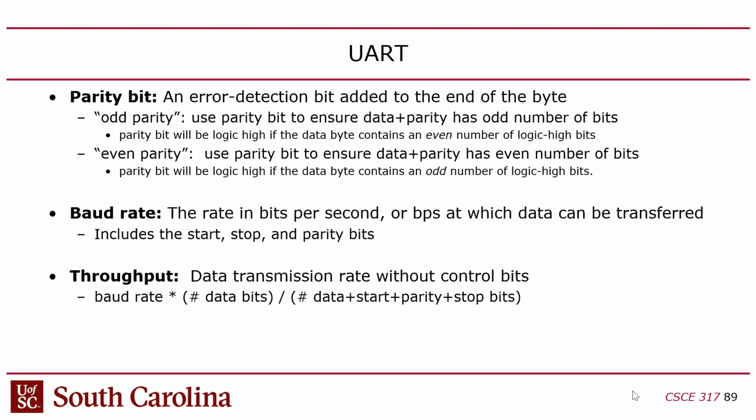Luckily, in this day and age, and in my experience, usually it's 8 data bits. Actually, there could be a different number of data bits too. I didn't mention that, I should have. Normally there's 8 data bits, but technically you could have more or less. But 8 data bits is the standard. No parity, and 1 stop bit. They call that 8 and 1: 8 data bits, no parity, 1 stop bit.